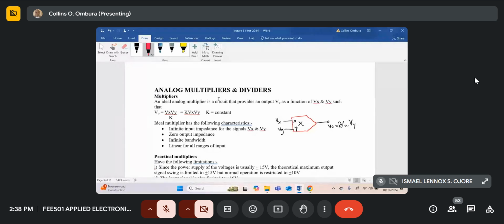Because in long distance communication, we need modulation techniques. And most of the modern modulation techniques use multipliers. Be it your FM, AM, phase shift modulator, QPSK, SSB, DSB, all those circuits require an analog multiplier. All these computer modems, they all require analog multipliers.